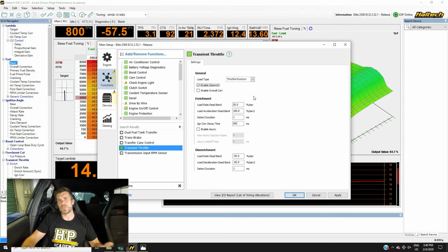So you might be wondering why under steady state conditions you're seeing erratic air-fuel ratios. This can be why. It's always a good idea for this very reason to actually inspect or log your acceleration enrichment parameters, so you can see if you're getting uncalled for accel enrichment. Off the top of my head, I think the number that I'm using here, 20% per second, is pretty close to the default Haltech value. So there or thereabouts should be a good place to get started.